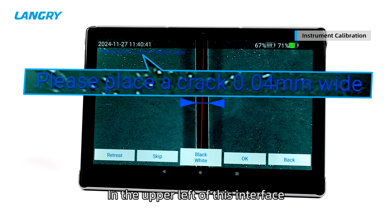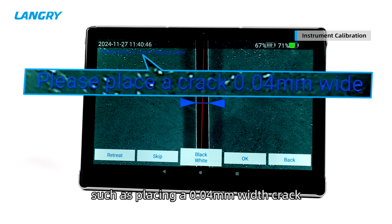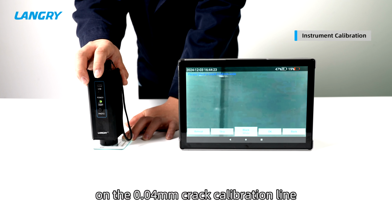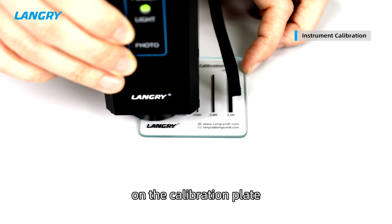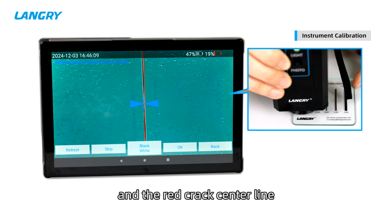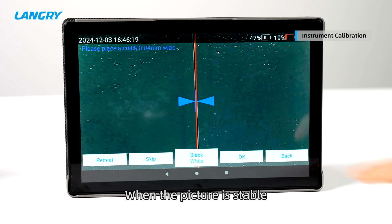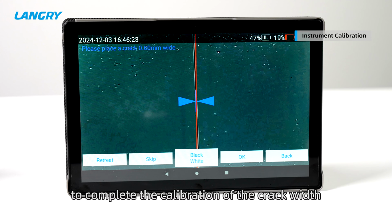In the upper left of this interface, there are tips for calibration steps, such as placing a 0.04 mm width crack. You need to place the probe on the 0.04 mm crack calibration line on the calibration plate. When the probe captures the crack, the screen will display the blue cross cursor and the red crack center line. Move the probe to make the cursor coincide with the center line. When the picture is stable, click OK to lock the picture. Then click Save to complete the calibration of the crack width.